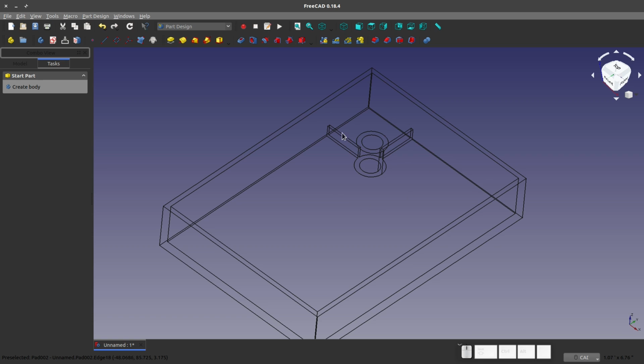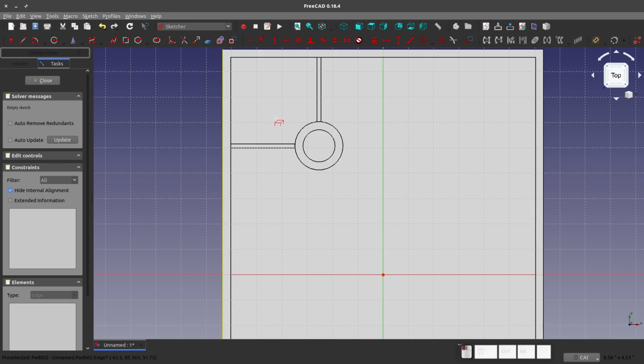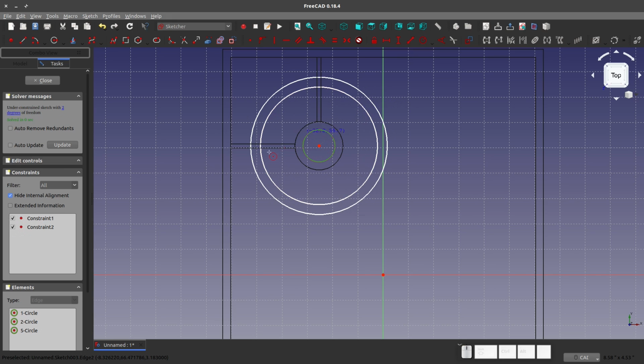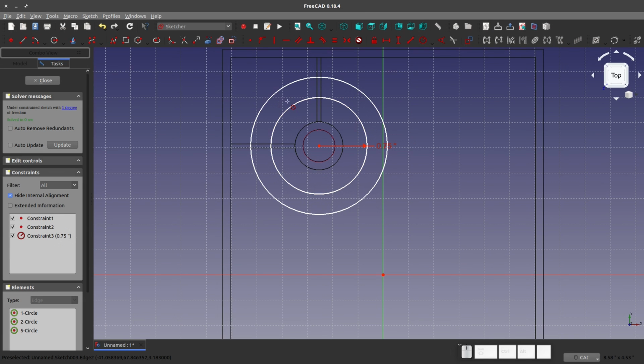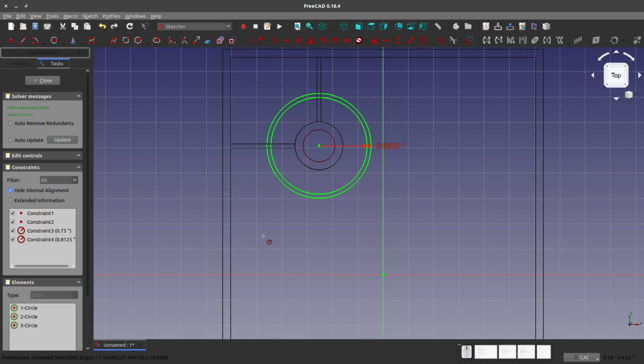Now let's say I want to have a circular rib to help reinforce these ribs. I'll change my draw style, choose this face, and create a sketch. I'll again import this edge. And for visuals, I can go back to my wireframe view. And let's create another set of ribs that are circular to support the flex on these ribs. We'll give this a radius of 0.75. And give this another radius of 0.75 plus 0.125 times 0.5. And there goes my circular rib.